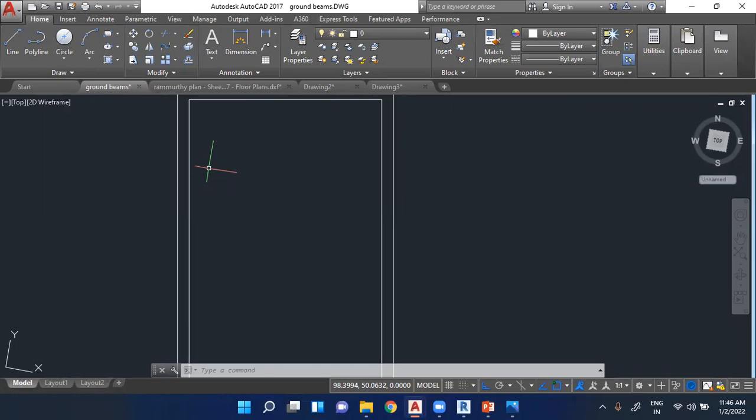First we visit the site and take the actual measurements and dimensions. Then we plot the actual site here. The client will give us his requirement, like a 3-bedroom hall kitchen, or 2-bedroom hall kitchen with a parking, or single bedroom hall kitchen, whatever he needs. He'll tell us, and we prepare a rough sketch.